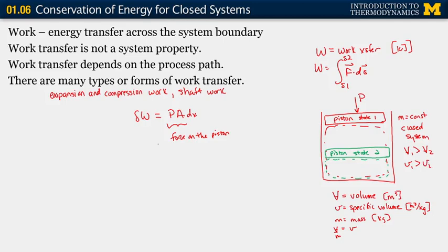So we come back over here and we say, okay, this is a force on the piston. We're going to execute that through some differential distance dx. So if this is x equals 0, and if we were to push this a differential step, that would be dx, right? But we want to actually evaluate this system over the entire process from state 1 to state 2. So we're going to integrate this expression on both sides from state 1 to state 2.